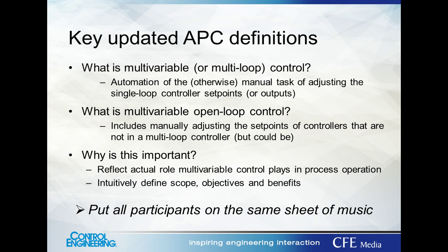By the same token, we can now say that open loop control, which used to mean manually adjusting the output of a single loop controller, now includes manually adjusting set points of controllers that have not been incorporated into an automatic multi-loop controller, but could be.